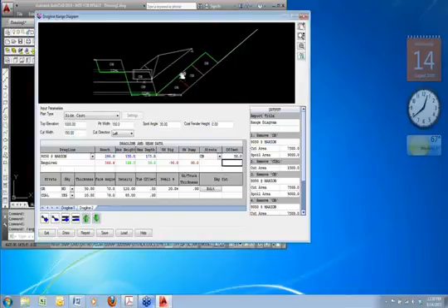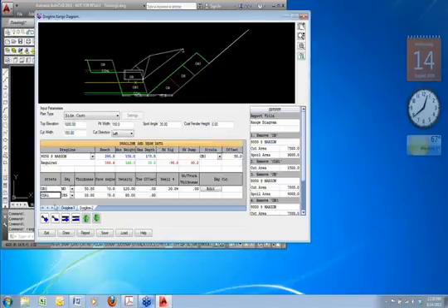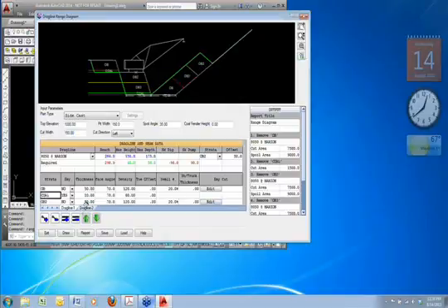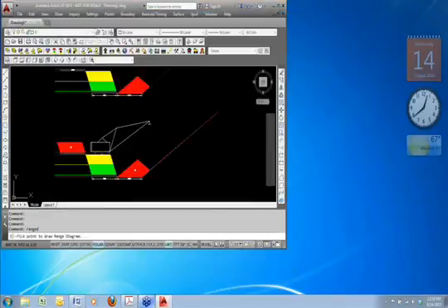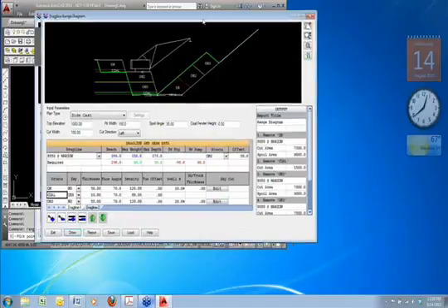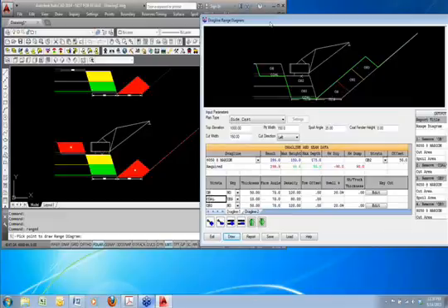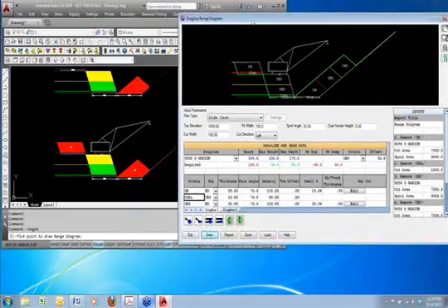So we'll go ahead and take this and show you the output. It's nice that it's color-coded and everything's labeled, so you can see where each overburden and spoil goes. I'll go ahead and change those names, OB, OB2, and OB3. So the first one would be drawing it in CAD. I'll just hit the draw button and pick a point to draw a range diagram. So it puts it in AutoCAD as hatch, polylines, everything's labeled, and you can plot from there. Color-coded, so you know what dirt goes into what spoil.